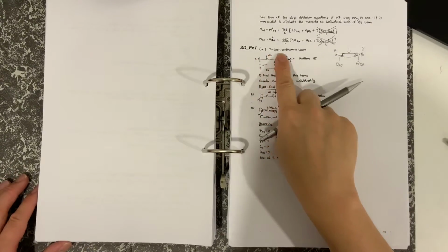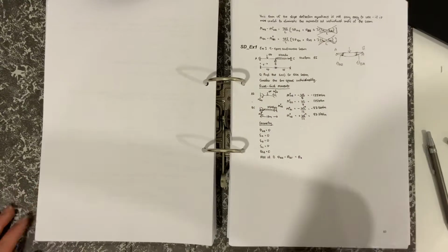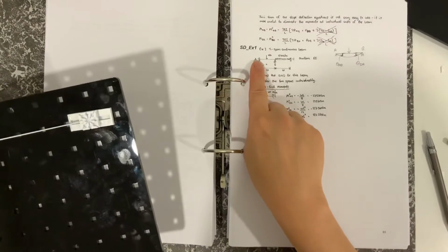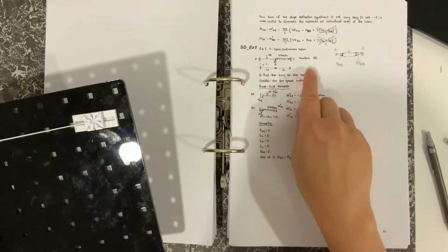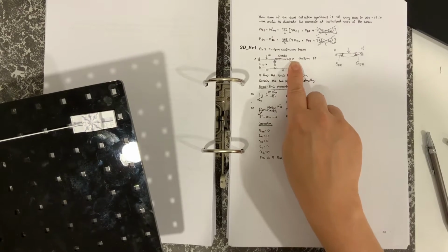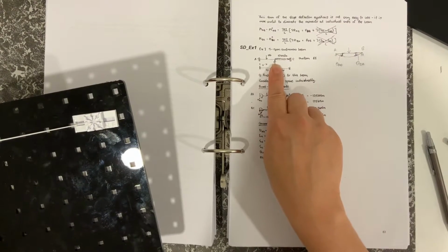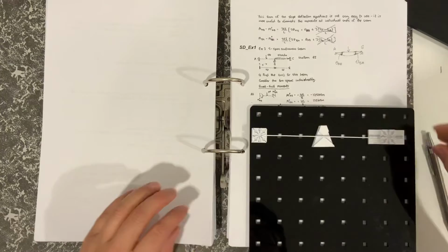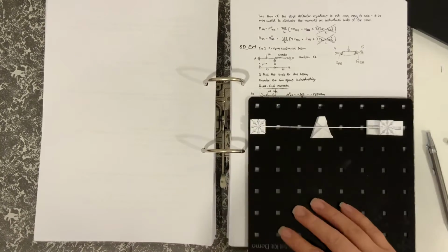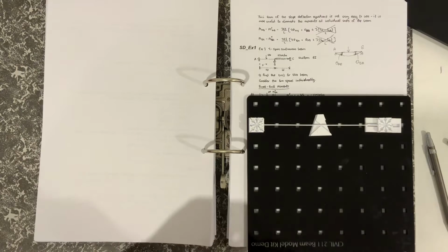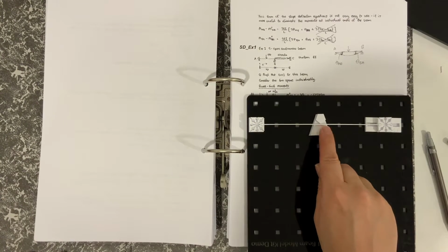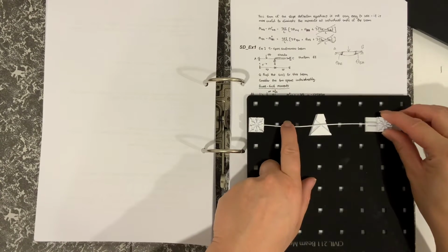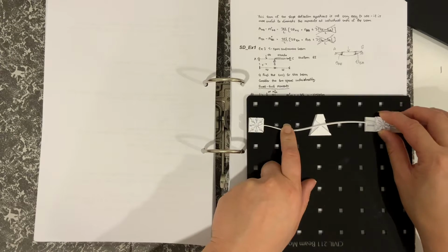Okay. So let's get on to an example. This one here is an example of a 2-span continuous beam. For a 2-span continuous beam, the left hand side is fixed, the right hand side is also fixed, and we've got a roller, or support, acting at the center. So that would be how I would want to show it. Now look at what happens here. So we've got 100 kilonewtons acting downwards.